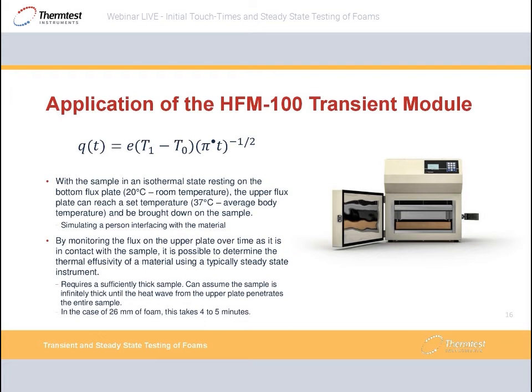Now, it's important to note this requires a sufficiently thick sample, and it turns out that we can assume this sample is infinitely thick as long as a heat wave from the upper plate is still diffusing into the sample and has not reached the other end of the sample. So in the case of our 26 millimeter foam mattress test sample, this takes about 4 to 5 minutes. So for 4 to 5 minutes, we can record thermal effusivity.